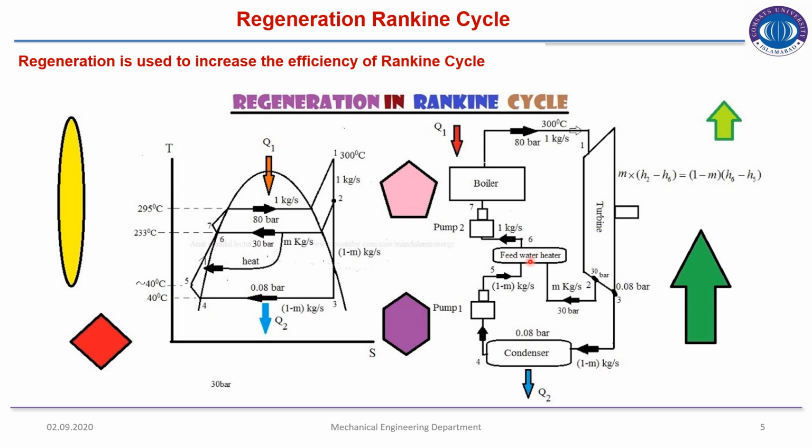0.3 kg of mass per second is entering. So that will be a steam. So steam is mixing with the working fluid. So now you see that here, up into the boiler. So look, the steam that is entering is 233 centigrade hot. So the temperature of steam is 233. So it will mix with the water and will increase the temperature of the working fluid.